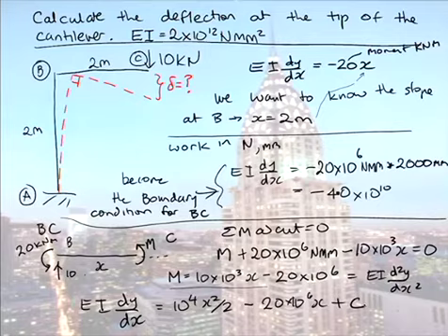Now it is at this point here that we can actually use our boundary condition, because the slope, as I drew in the other picture, here is actually equal to the slope going around the corner. Because it's a corner, it stays at 90 degrees, and however it rotates in the vertical is how it rotates in the horizontal.